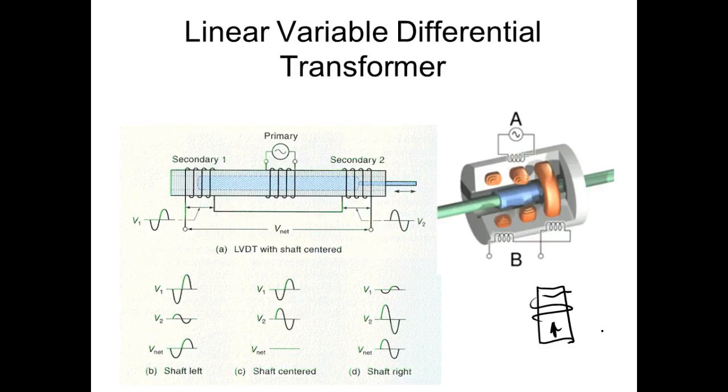Your transformer would get very hot, for number one, and you'd get almost no energy through it. So we take this core and break it up, split it into individual little plates. We call it lamination because they're coated with a paint that electrically isolates them from each other.